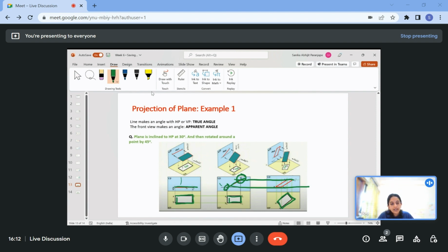So A and B both are here at this height. I will project A here. I will project B also till here. And since I've rotated it like this, but my heights are still the same, my C will be extended till here and D will also get extended till here, and that is how we get the parallelogram.